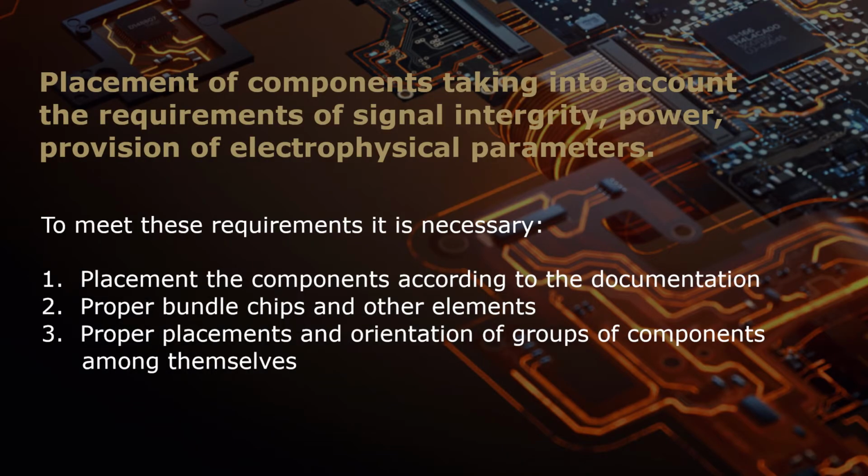So again, you're going to have some specific requirements. If you have specific assembly requirements for your PCB, of course, talk to your manufacturing engineer for fab and assembly, because remember, placing footprints on the PCB is really all about assembly.